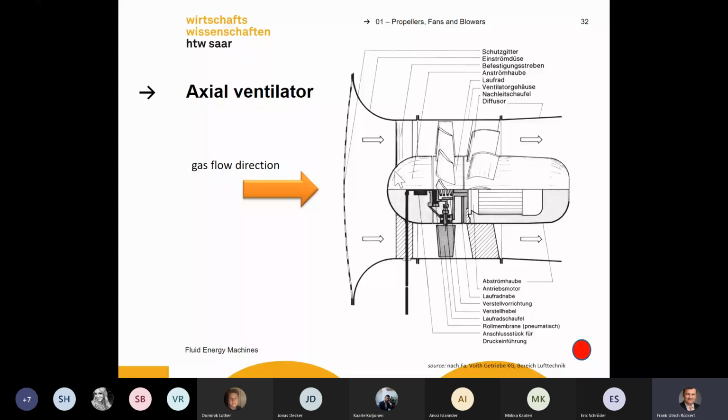The design of the nose is also important for efficiency, and you have a duct here. And the design of the duct is also really important for fluid flow and for efficiency. We don't want to produce too much turbulence in this ventilator, because turbulence is always loss and friction.